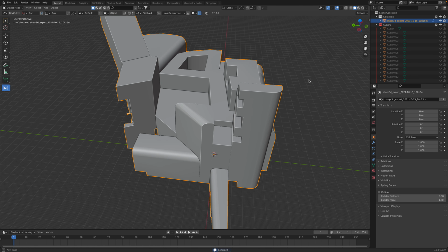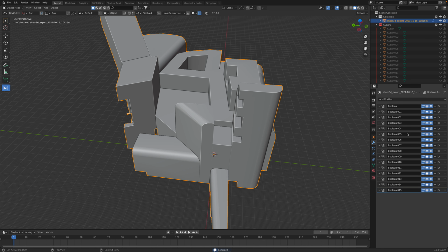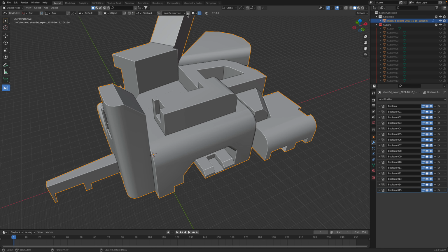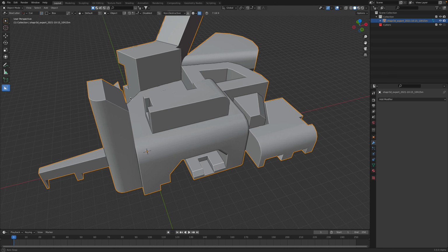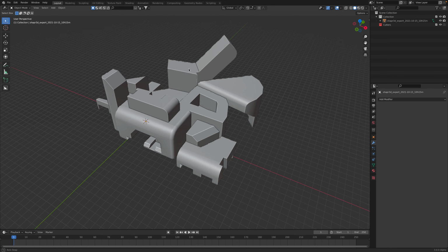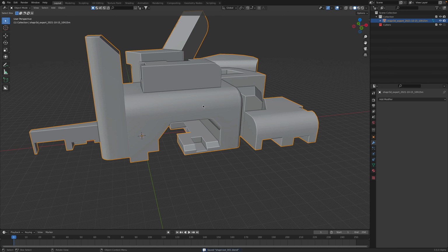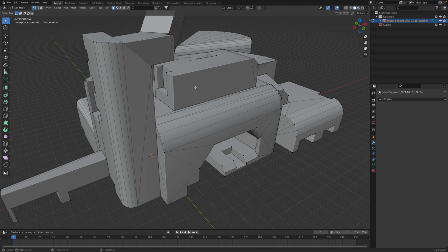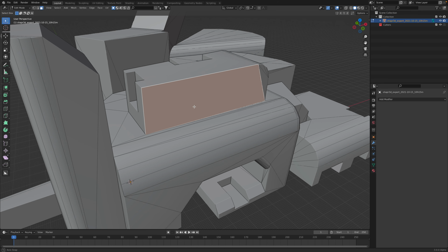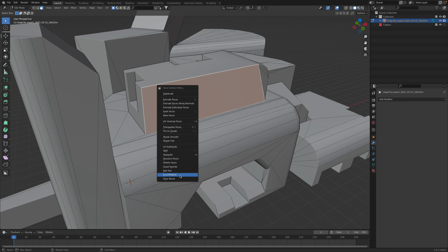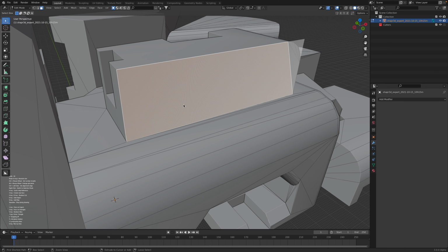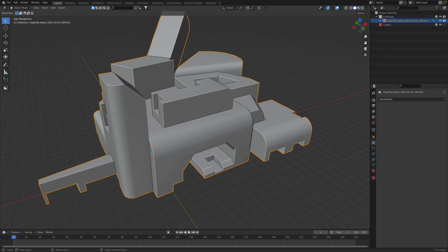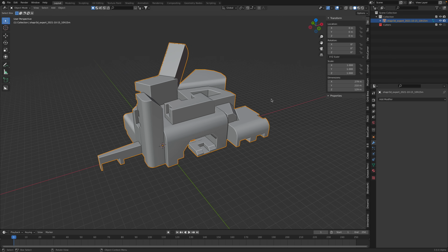It's drawing all this history, right? This is Boolean history. We can just apply all the booleans. This is BoxCutter, right? Besides BoxCutter, I also like another add-on called GridModeler. You can select any face, right click, and then create a grid. Very similar to Shapr3D.